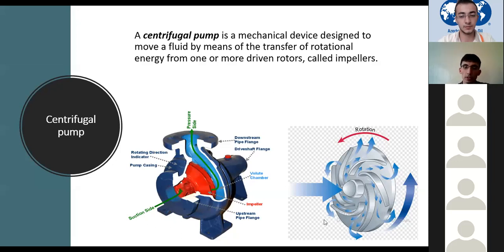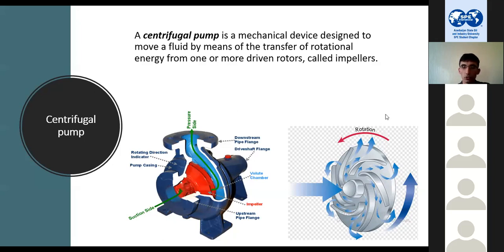As the impeller rotates, it creates suction at the inlet of the pump, because it increases the velocity and what's called the velocity pressure inside the pump. This is why suction is created at the inlet, and in this way it can generate high pressure for fluids.